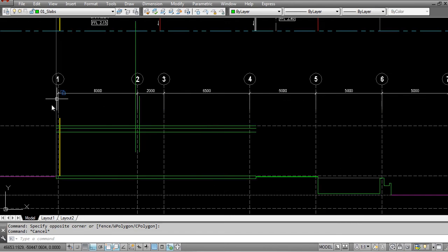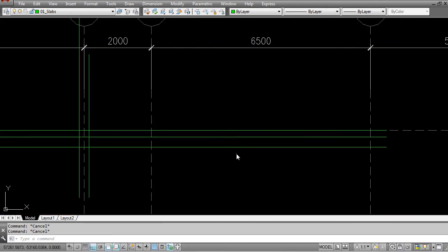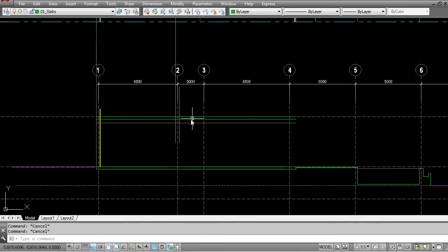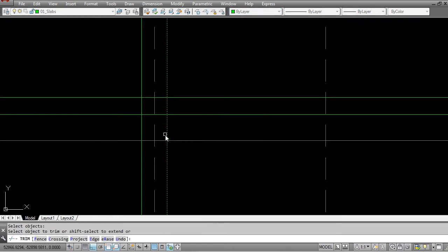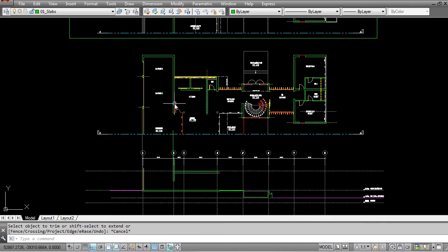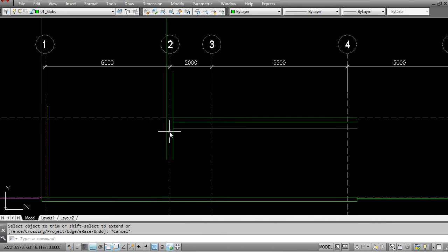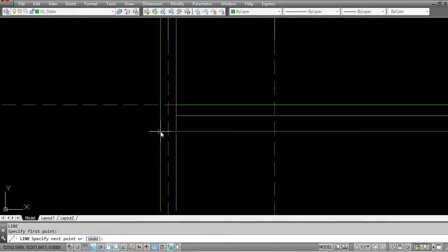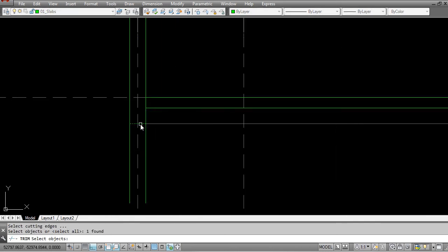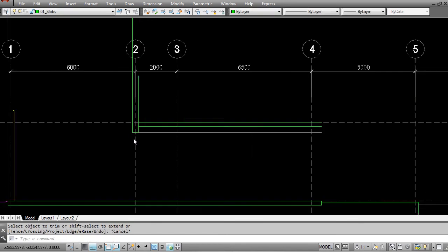So I can see in a later design revision if I want to actually add a ceiling that conceals all of this, or if I want to have an exposed slab. So for now I'm going to leave that beam in there until I do a little bit more design development or research on that. So I'm going to use the edge of this wall to trim that, and this wall actually will run down, and basically it will start where that garage adjoins into the living or dining area.